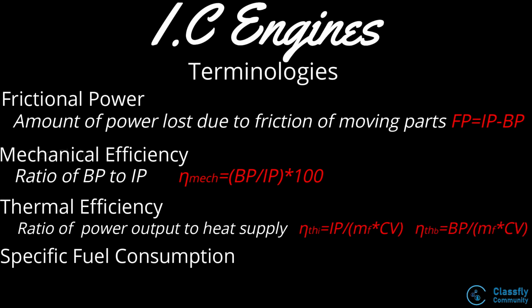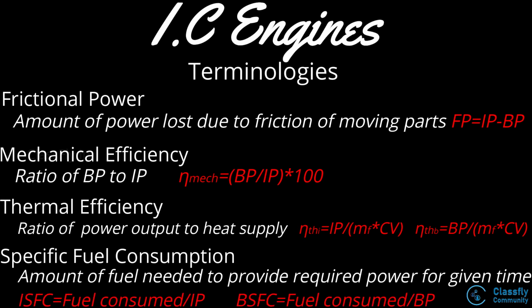and then the specific fuel consumption, which is the amount of fuel needed to provide the given power for a given time period. Hence, this can be given in terms of indicated power and brake power, that is, ISFC is the fuel consumed divided by the indicated power and BSFC is the fuel consumed divided by the brake power.